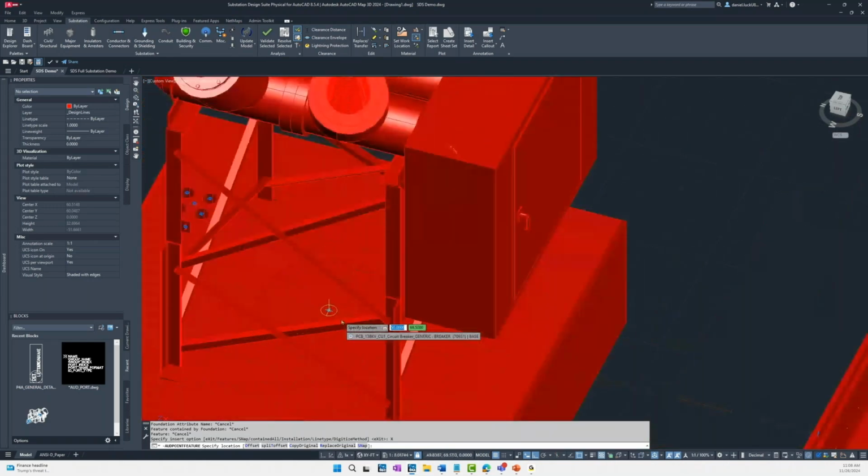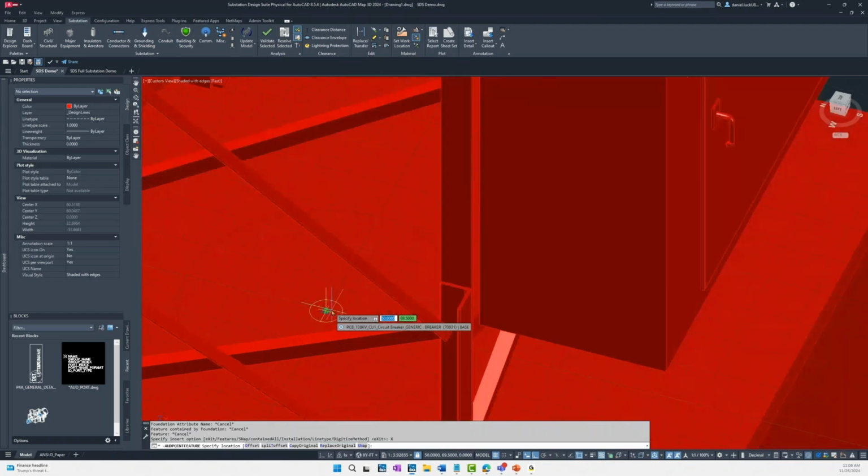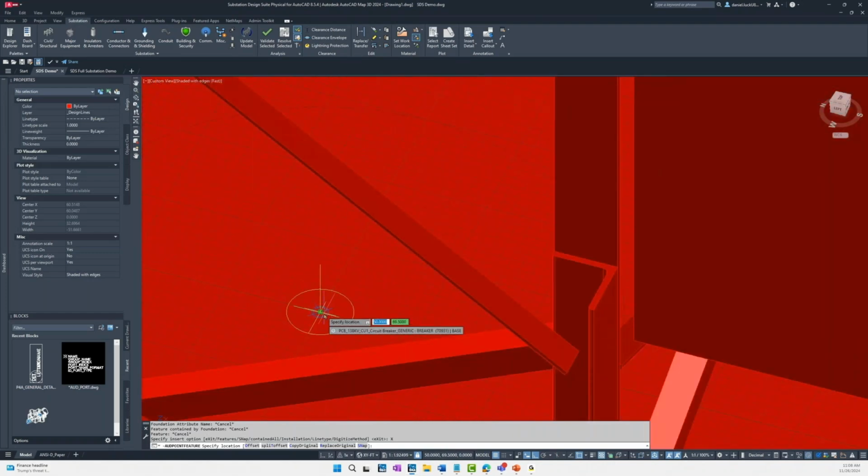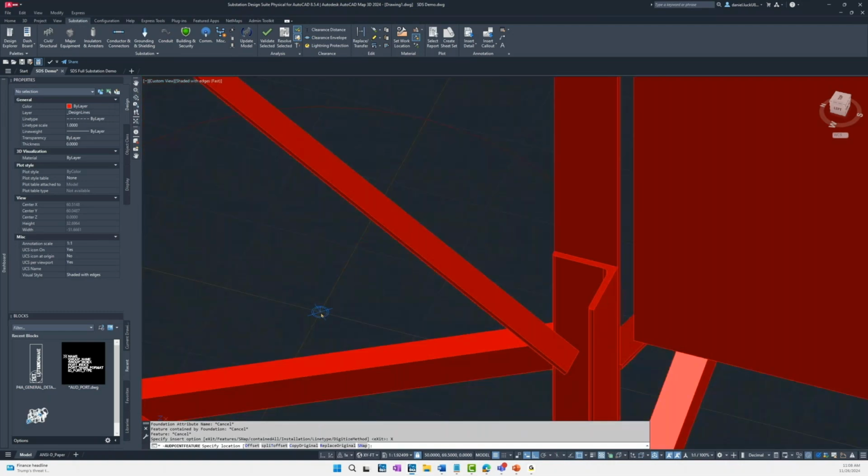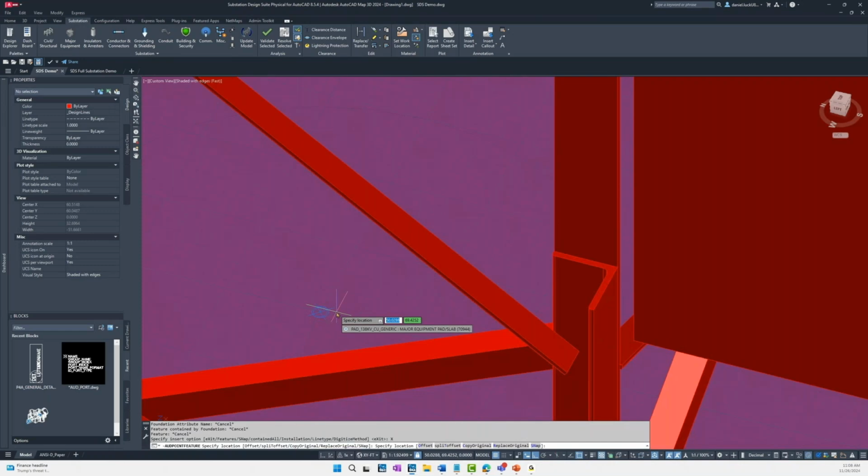As we hover over this port here, you can see we get this little yellow arrow pointing in the up direction. And then a box pops up, and it shows, PCB 138 kV circuit breaker. And this is showing that this foundational pad that we are connecting is being connected and contained by that breaker. And we can get into connectivity and containment here in just a second.